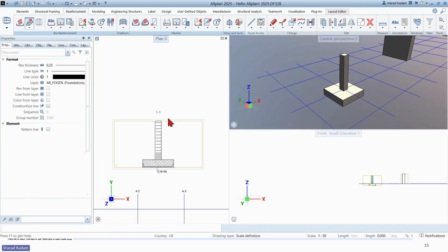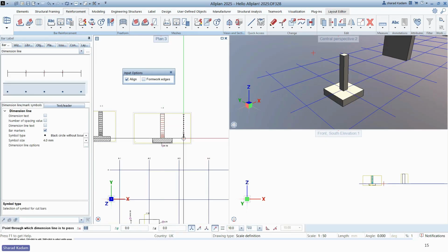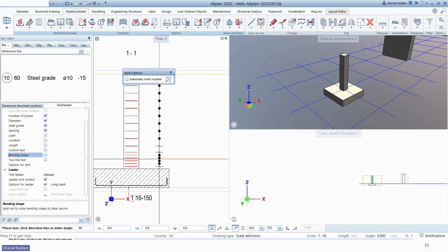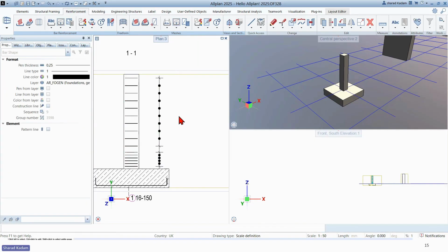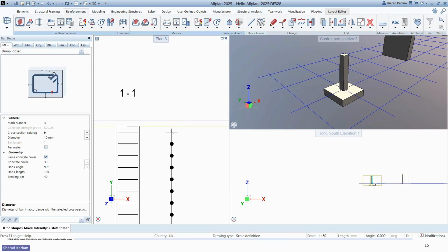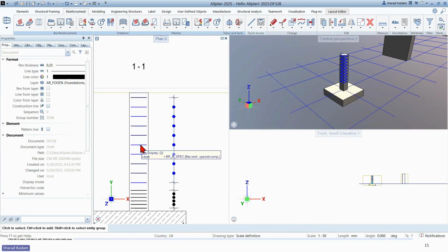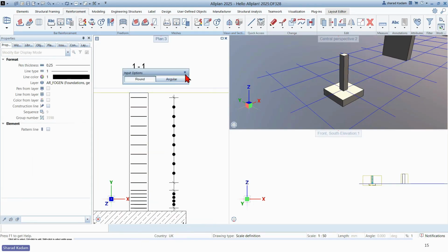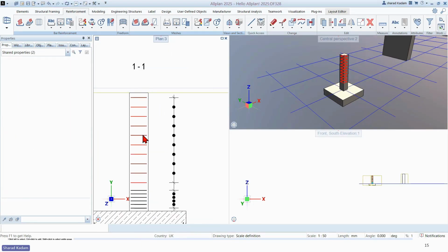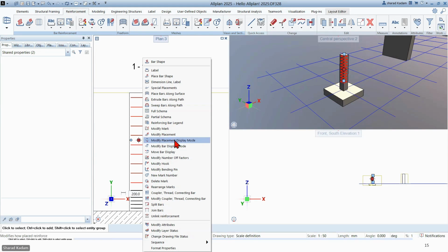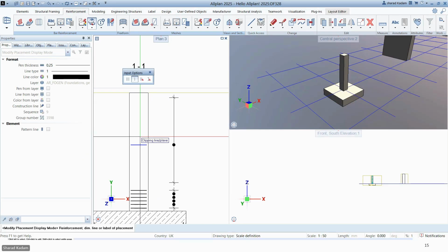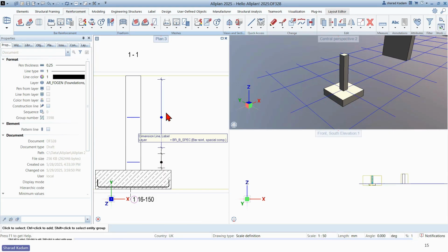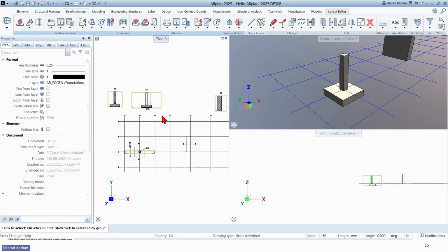So we don't need to worry about putting multiple ranges, multiple rebars, and side by side we can give the call out as well. So let's just give the call out over here and place the rebar. Okay. So again, if I need to show only a few bars, we can just click it and use display mode, so that it will automatically give the tagging as well as the name. So like this we can do it.